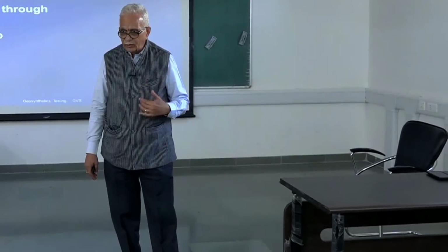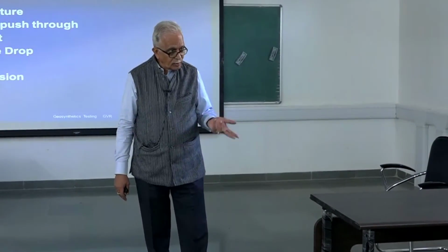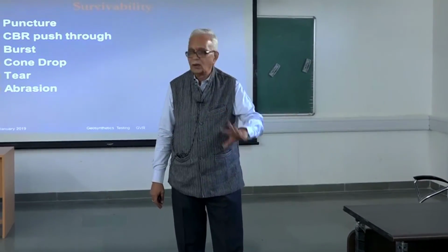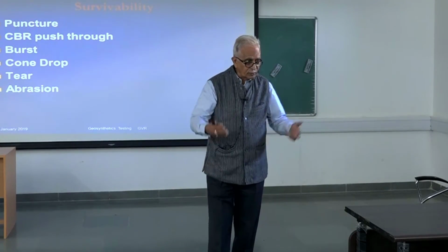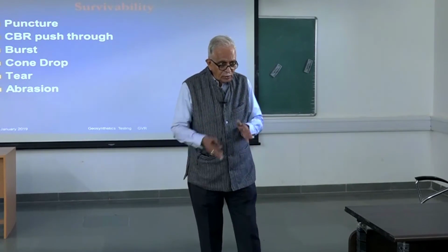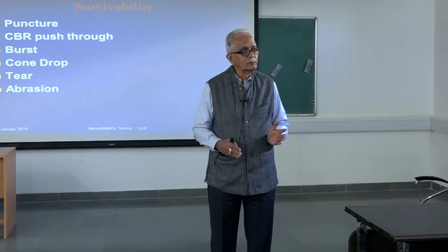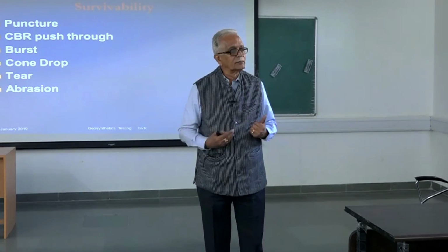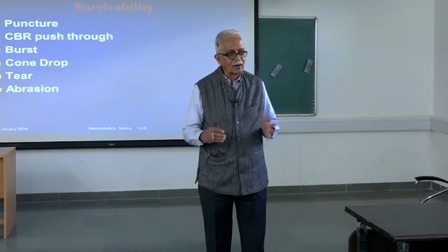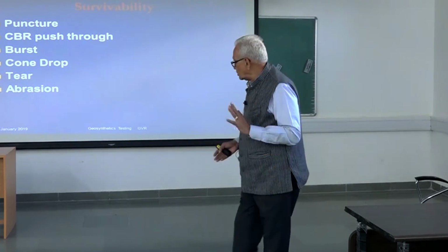In the same way, if the cover soil is clay, damage is going to be less. If the cover soil is aggregate kind of thing or gravelly, naturally damage is going to be more. Like this, we have to imagine. So the factor of damage due to construction will depend upon all these features of construction. Okay, there is no standard value for that. So that is something you have to keep in mind.